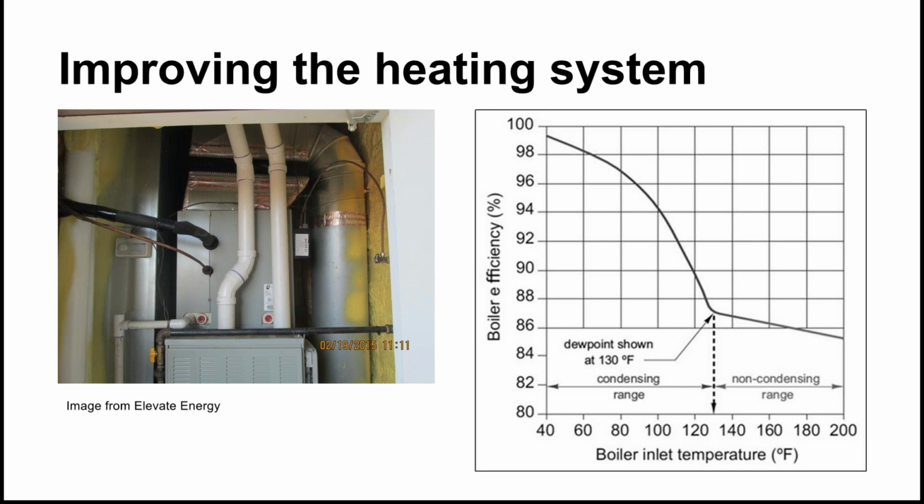So if you have a lot of spare capital lying around, a good way to save a ton of energy is to switch to a high efficiency model for a gas furnace, for a boiler, a heat pump, anything like that. So there are a lot of ways to heat a space. These all use combustion to heat either air, in the case of furnaces, or water, or converting water to steam, and that's what flows through radiators, water, steam. And you can improve the efficiency of all of these.